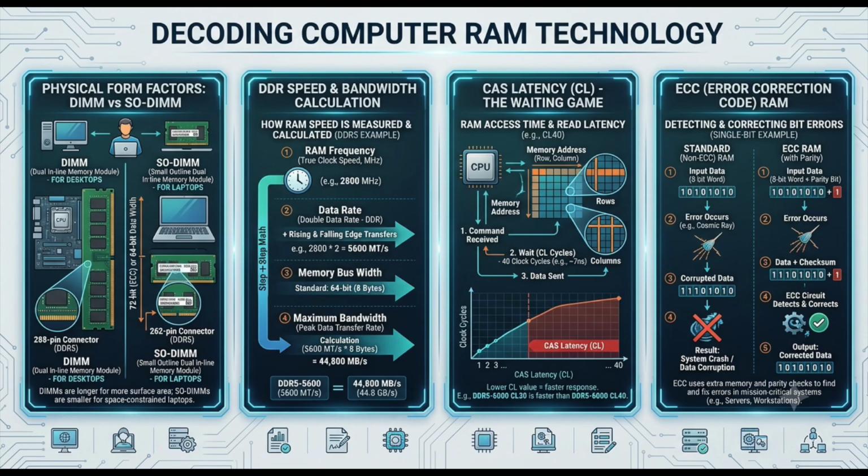So it refers to the electrical contacts. If you take a DIMM, that rectangular printed circuit board, and you look at the bottom edge, you will see a row of golden pins. The little gold teeth. Exactly. Now turn it over, and there is another completely separate row on the back. So dual inline means those two sides are completely independent electrical pathways. When you snap that module into your motherboard, it establishes a data width of 64 bits. 64 bits. Okay. So every single time the system talks to that DIMM, it is communicating in wide 64-bit chunks of data. Every single time.